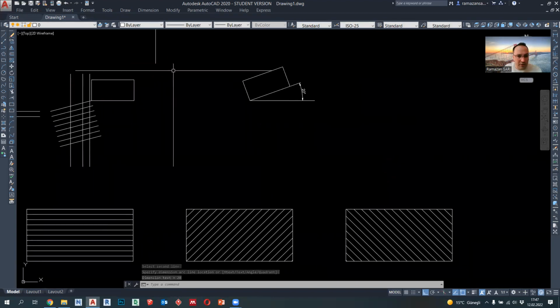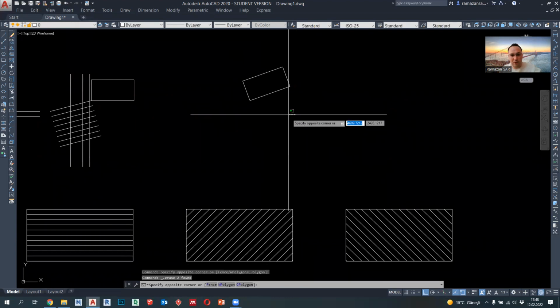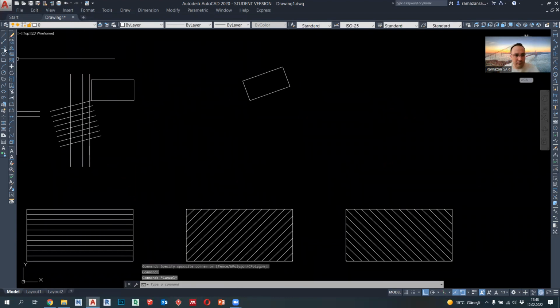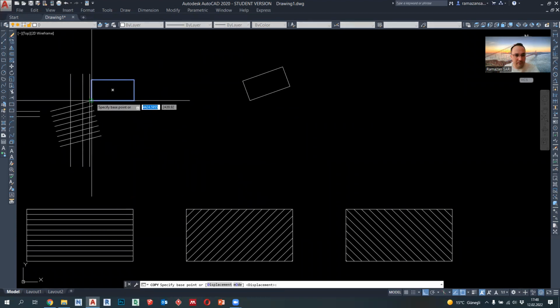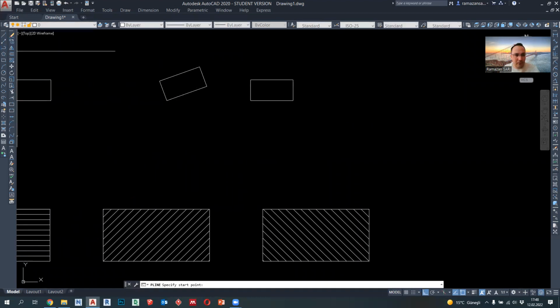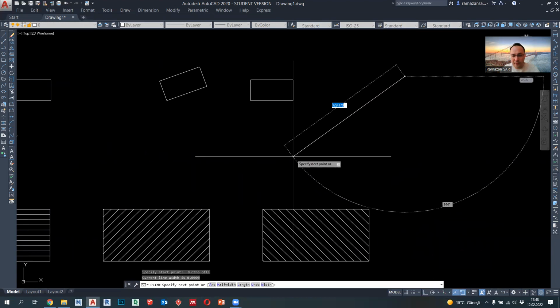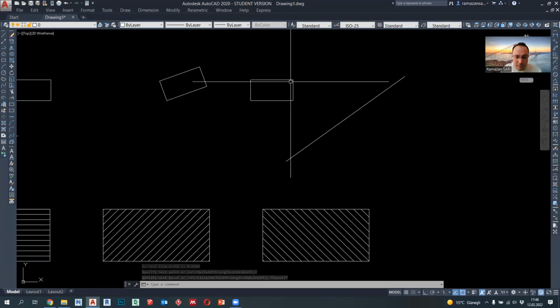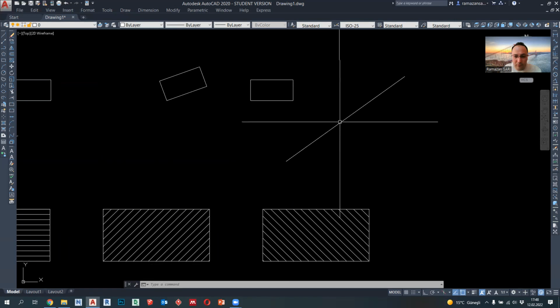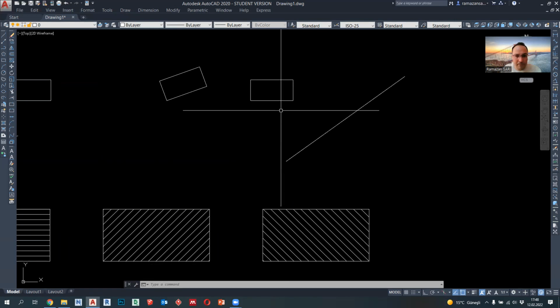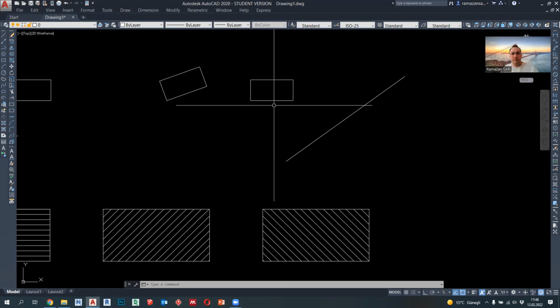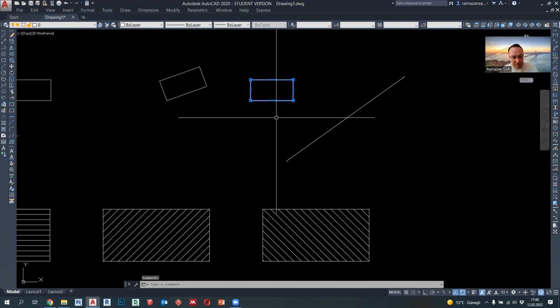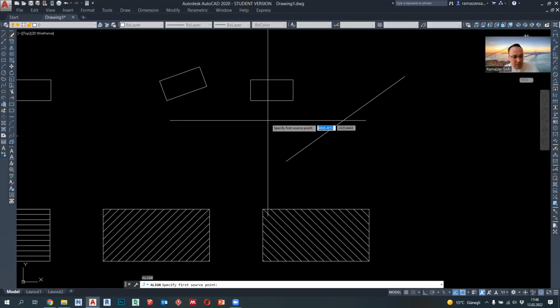Another method for objects, let me show you, which will be helpful for you. Let's copy this object again, and let's create an inclined surface having random angle. Assume that we will both rotate this object and align to the surface of this line. Which command will we use? Initially select your object and enter AL, the shortcut of align command.